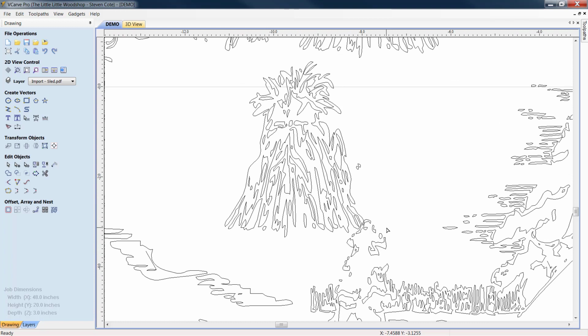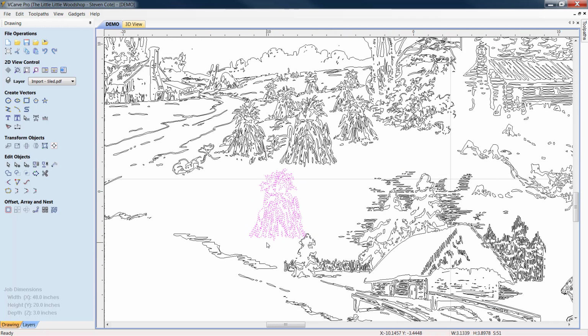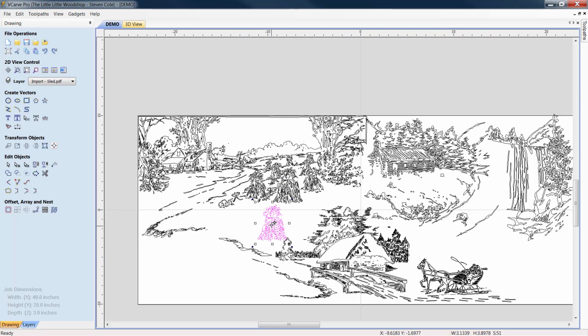We've got whatever this haystack thing is. I don't know. Edit Object Selection Mode. Hold down your left mouse key. Delete this stuff out. We're going to come over here and we're going to highlight this one, holding down the Shift key. Let's highlight and get all these lit up. Now what I want to do is move the haystack, or the stack of corn cobs, over here to the side.